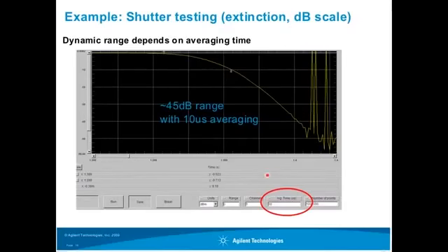Okay. Here's now a case, same thing with a faster measurement time, trying to look at what's happening. So now we're at 10 microseconds, and here the noise picks up already once we get beyond about -40 dB. Got a couple of funny points here. These are just how my software was handling underflow points. Those are points where the power meter is giving a negative value because, due to the noise, it's got a signal lower than what the zeroing level has defined as 0 power. So there's nicer ways to handle that. I'll show that later. But that's kind of the effect. The faster you measure, you start to give up the dynamic range of the measurement. So that's a compromise to make in setting up these kinds of measurements.